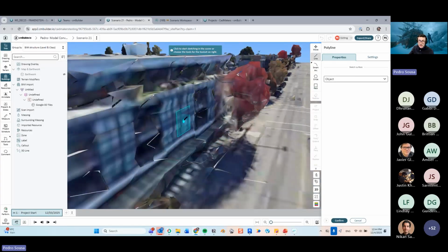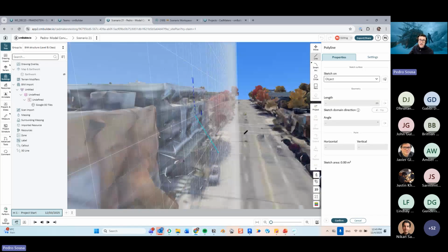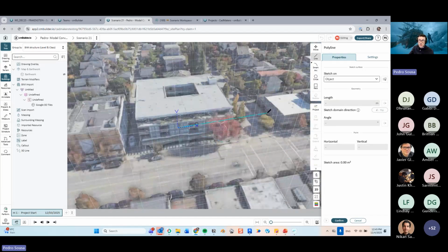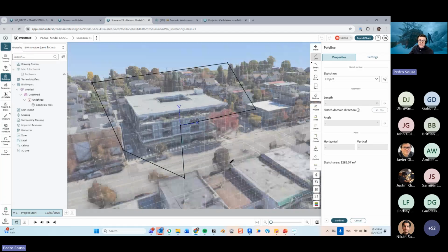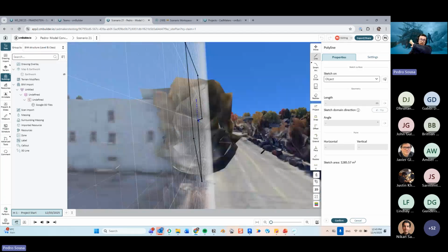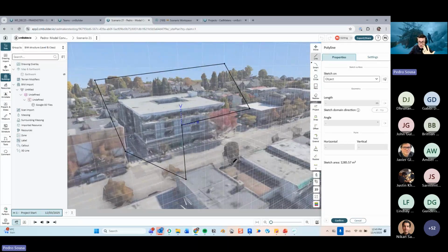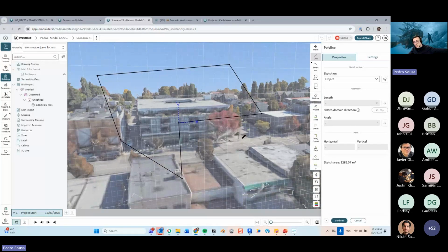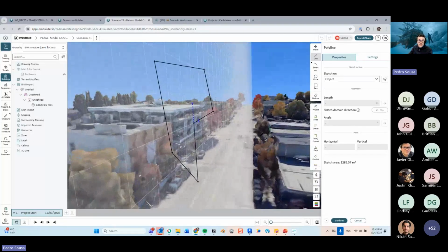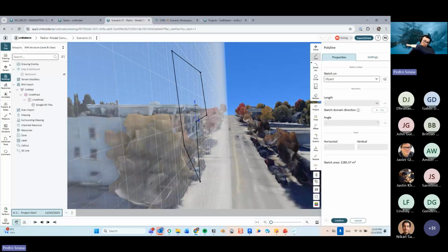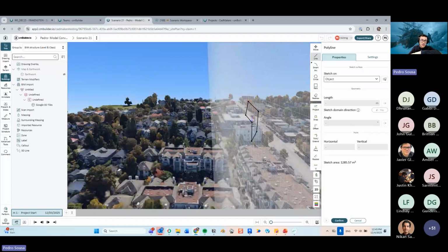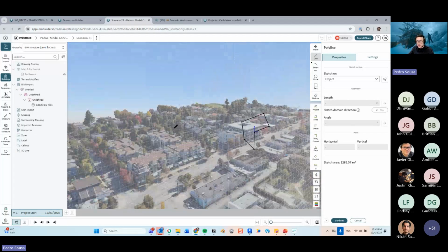So as you can see, if I place my sketch on the exact same location that I had the other one, this sketch will be vertical. So whatever I draw over here, in terms of splitting this geometry, will be applied orthogonal to this sketch. So this is why it's important that we select the correct faces, right? For example, if I wanted to do a horizontal split over here, this split that I drew is not gonna help with that because it's gonna be orthogonal to that face, and it'll propagate all the way up to the end over here, and slice a bunch of other geometries, you know?